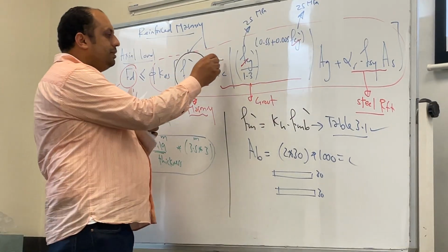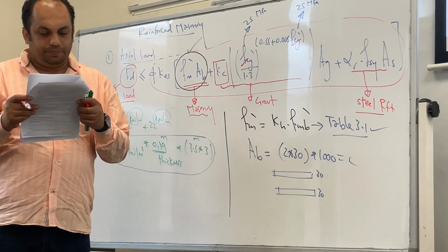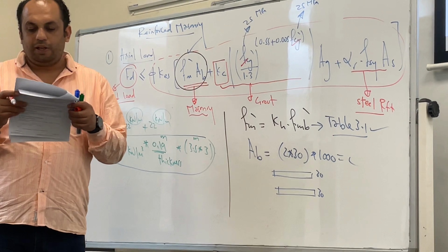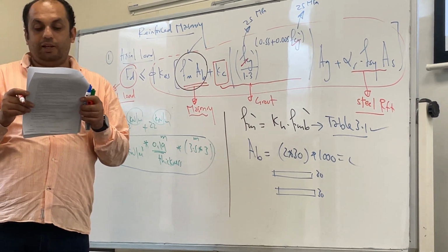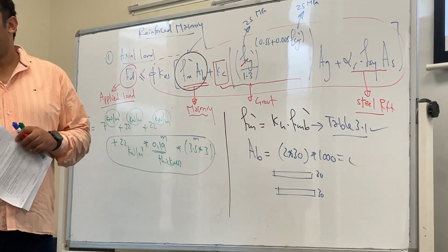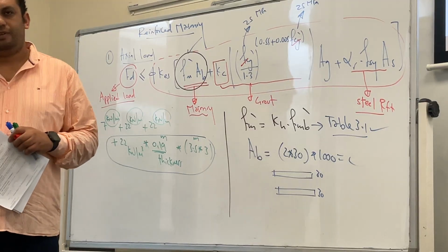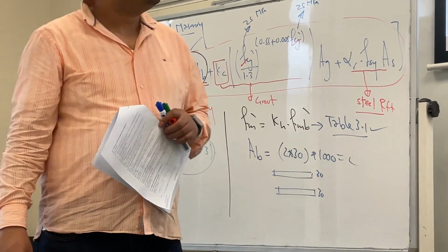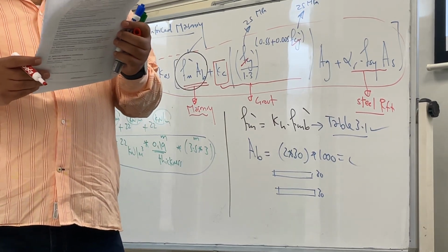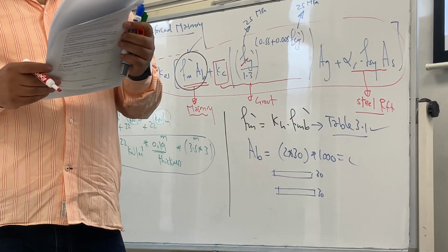So what is kc? kc is 1.4 for hollow concrete masonry greater than 2000 kg per cubic meter, or 1.2. So how much is it? 1.4 or 1.2? I'm pretty sure it's the last. I took 1.4, because it's 2,200 kilograms per cubic meter. Yeah, I got 1.4, the hollow.